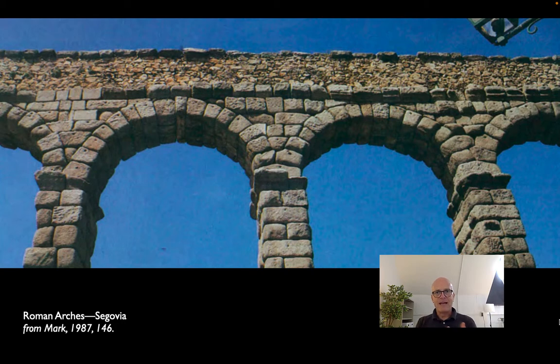To make sure that any localized imbalance gets taken care of, between the two arches, there's a very, very heavy pile of stone shaped in a sort of upside-down triangle, and that actually has the effect of pushing or changing the trajectory of the arch's thrust toward the vertical, so lessening the amount of resultant thrust in one direction or another, making the other arch's job easier, basically, in resisting that thrust.